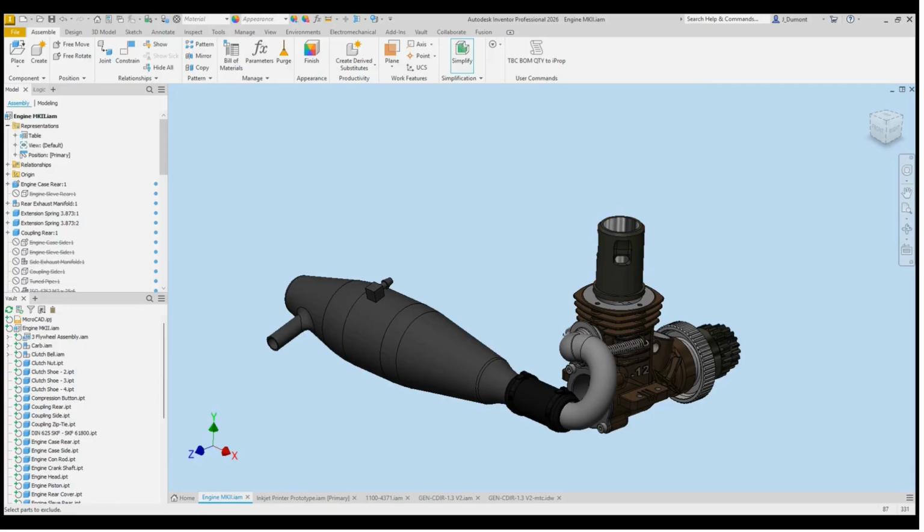You're going to see I have 87 components at the bottom right, and I have 331. For those of you who are not familiar with these numbers, 87 is the total number of unique components, and 331 is the total number of components I have in the assembly. So I have one fastener, or let's say I have 5 fasteners. I have one instance of it, and the other 4 are copies, or instances. So you've got one primary and then 4 or 5 that are installed. So you'll see 1 and 5, or in this case, 87 and 331.